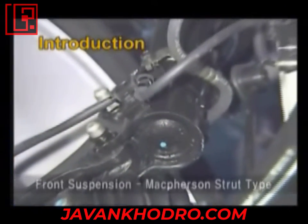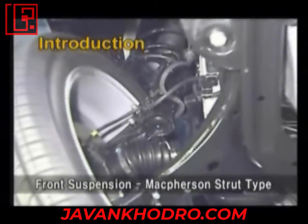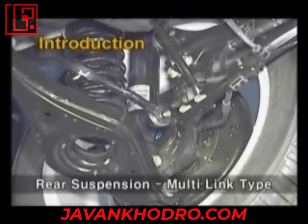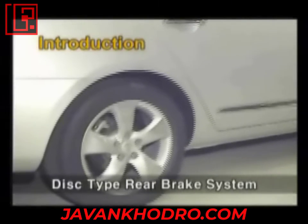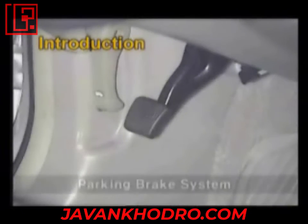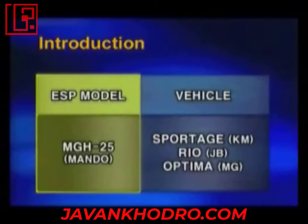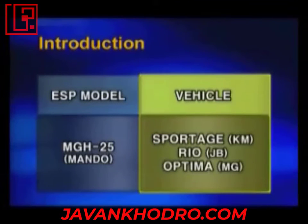The front suspension is the McPherson strut type. The rear suspension employs in-wheel type multi-link system to enhance the riding comfort. Disc type rear brake and foot brake type parking system are applied. For the vehicle dynamic control, Mando MGH25 ESP system is applied as an optional item. MGH25 series has been adapted for the new Sportage, Rio, and new Optima.